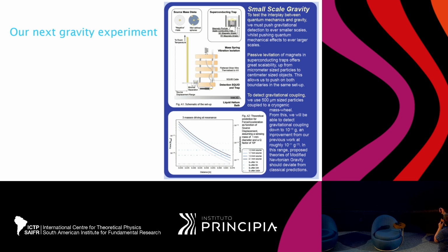This has either mass attached to it, or holes drilled in it to reduce the mass in these spots. Again, you go for an odd number of these, so 3 is one example. Then you spin this in a flat geometry as close as you can to this, and we think we can reach a centimeter.